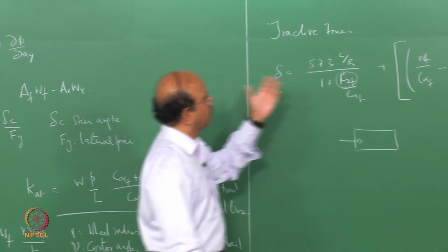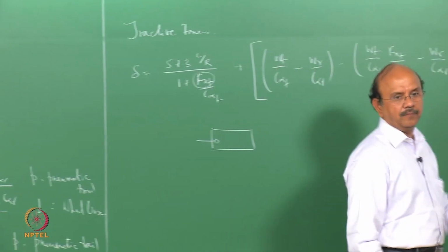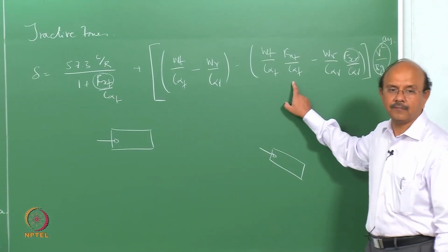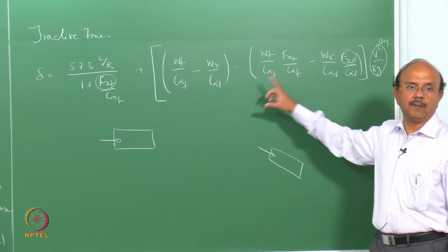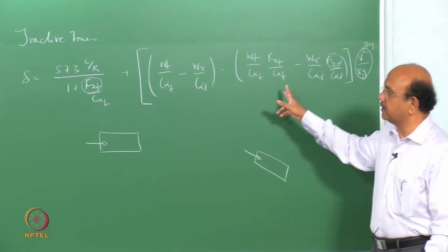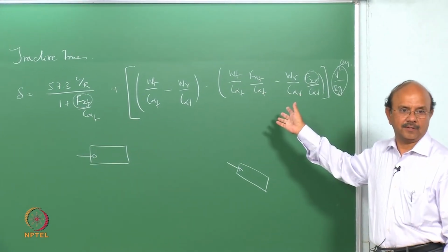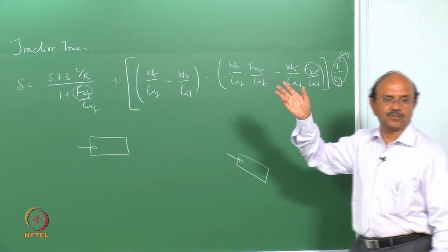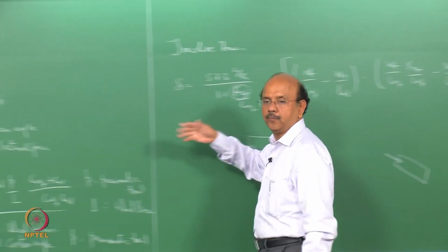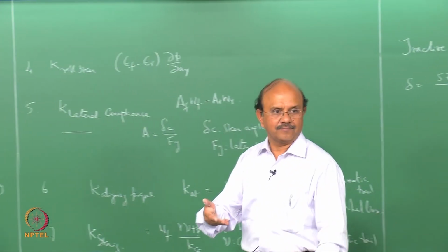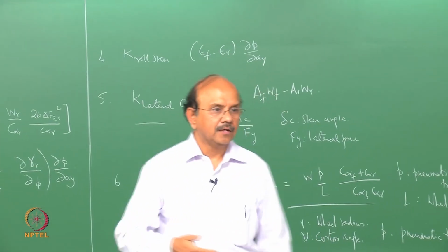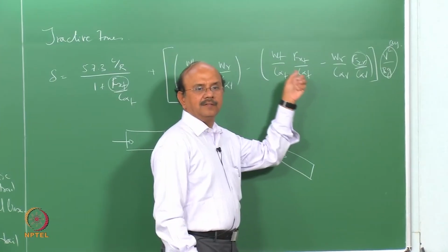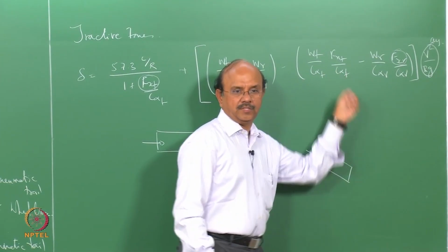Okay. So you will understand here in every term here. For example, if you look at this term, there will be a minus, so it will become an oversteer quantity. So delta is less, which means that it is oversteer. Okay. So delta is less here because there is a minus term here, the car tends to oversteer.